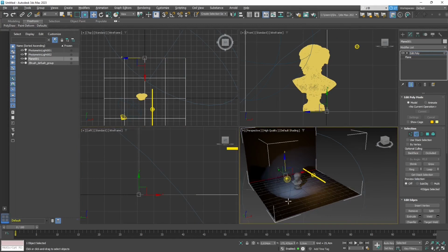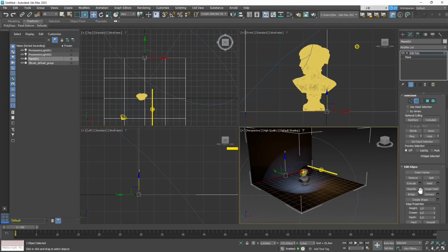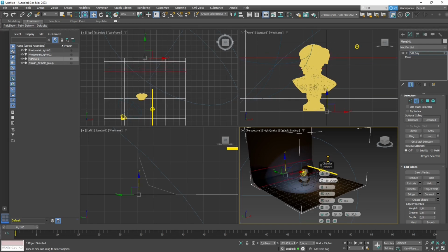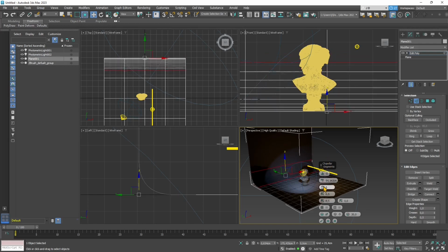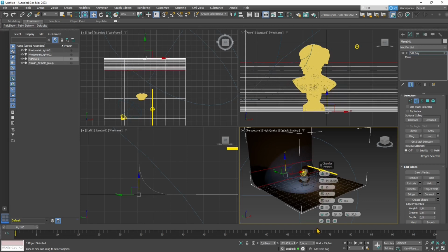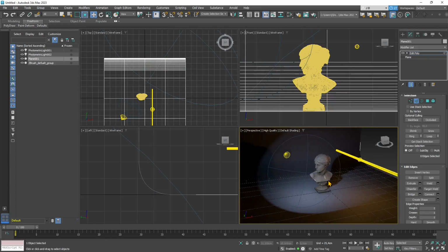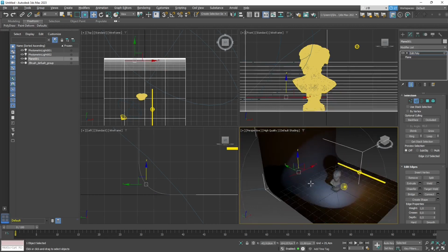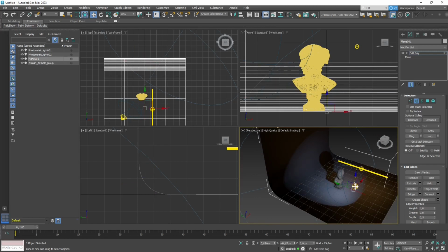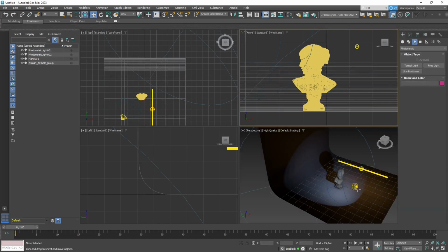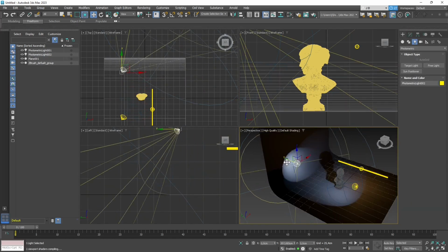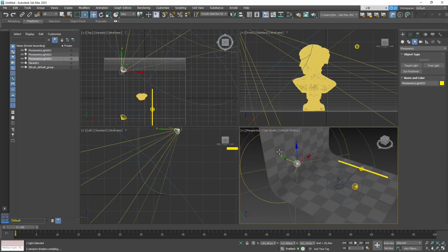really standard. Now I'm gonna select also those edges here and use the chamfer modifier in the polygonal editing tools, so that we can create a nice rounded connection between the vertical wall and the floor. So this is usually how a studio setup is prepared. So we can test better all our lights. To understand the lights better, you should always place them near a wall so that you can actually see the effect of the source.